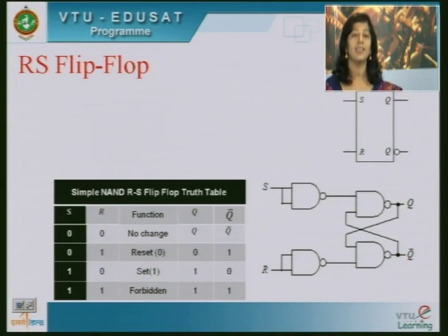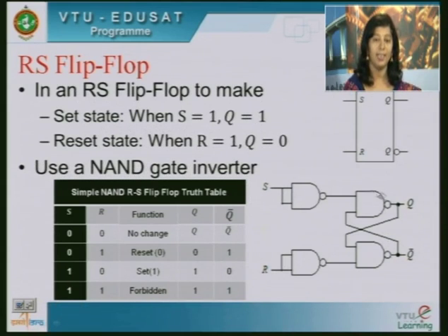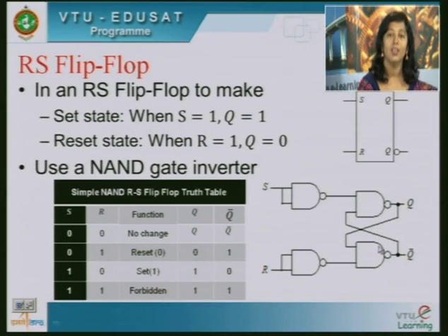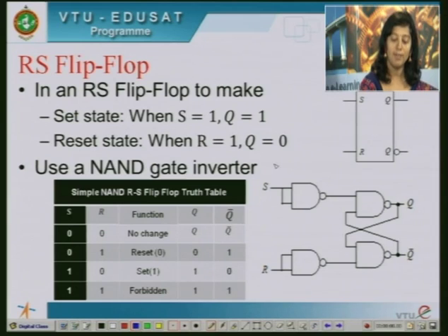Next, let us see what an RS flip-flop is. An RS flip-flop is just an extension of this latch, the NAND latch which we used. You can see the same NAND gate latch here as we have shown before, but I have two more NAND gates connected as inverters. The idea behind that is, whenever set is high, output Q should be high. Whenever reset is high, I want Q to be made 0.